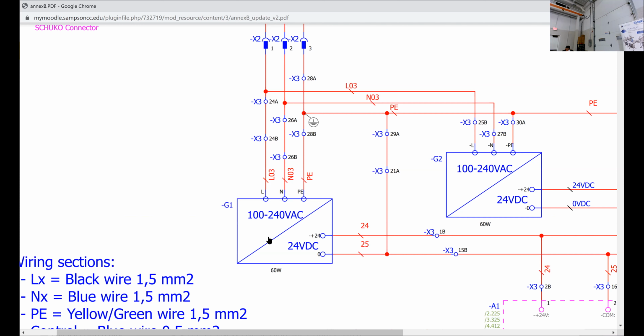You see two here. There's two on this one. And there's three on this one. This one has two power supplies for the 24 volt. One of them is for the conveyor motor. The other one runs the valves. And the other one is a 5-volt power supply, 5 volts that runs a 5-volt grid. So the little small power supply that you'll see, that other one is small. It's a 5-volt DC. They all have at least two power supplies.